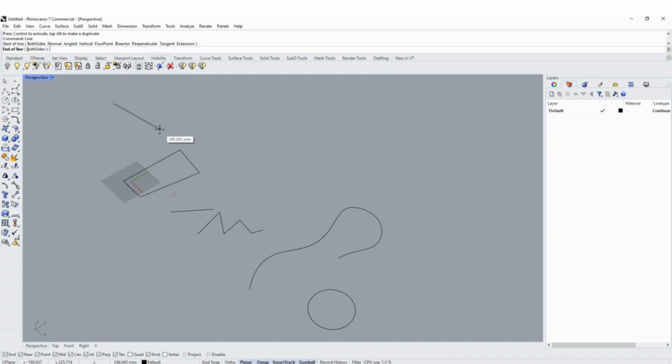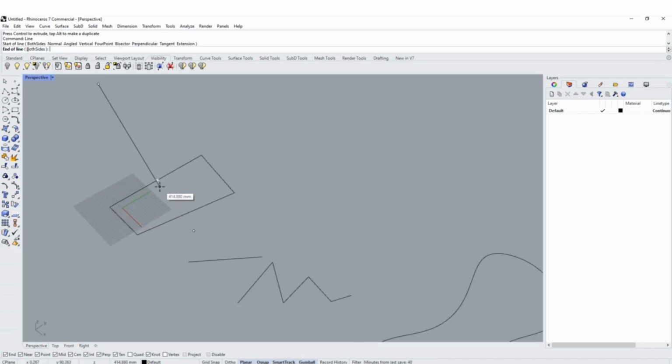Start point of the line, and let's say I want to stop in the middle. I want my line to be finishing exactly at the middle of the shape. Then I can actually use that, because you saw that it was highlighted middle. Because I have on my snaps, I have selected that I can be magnetically attached to the middle of any line or any object.